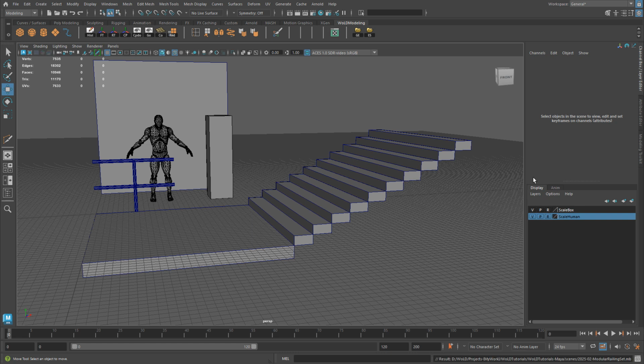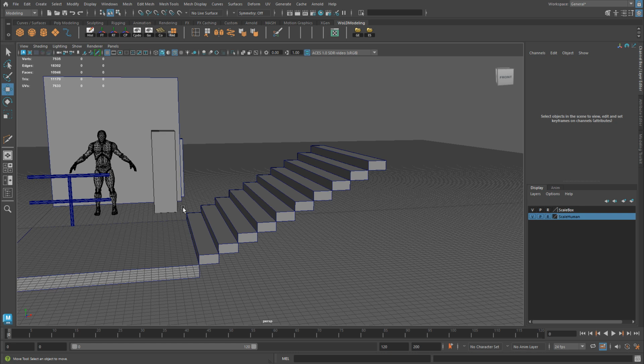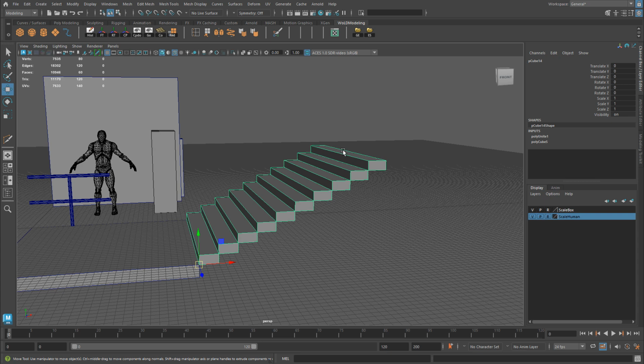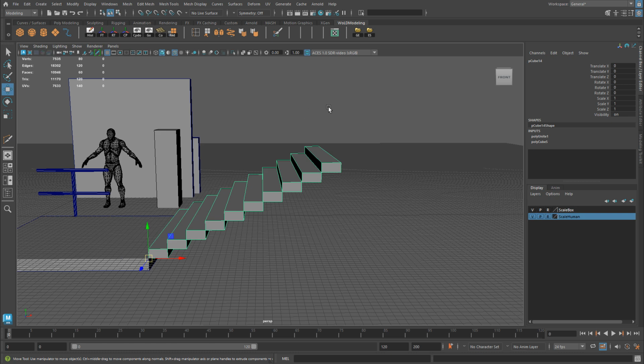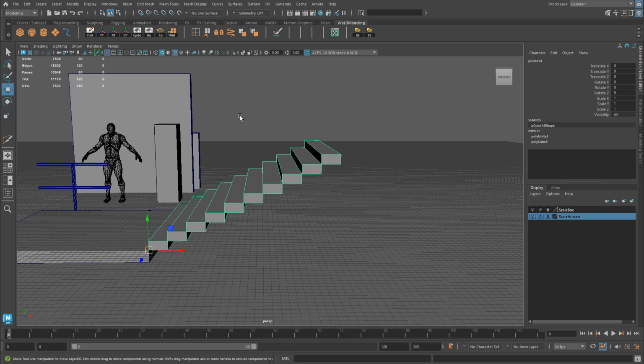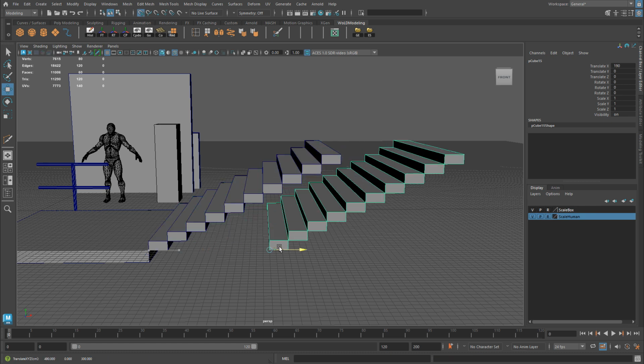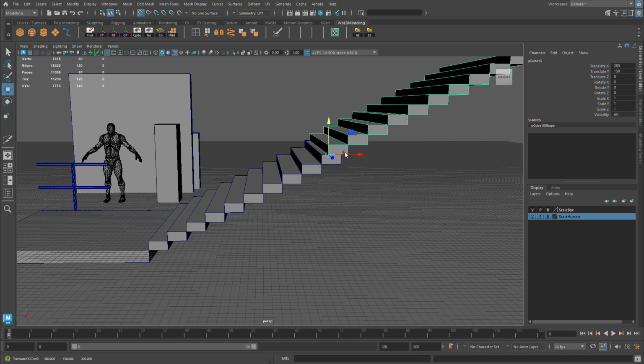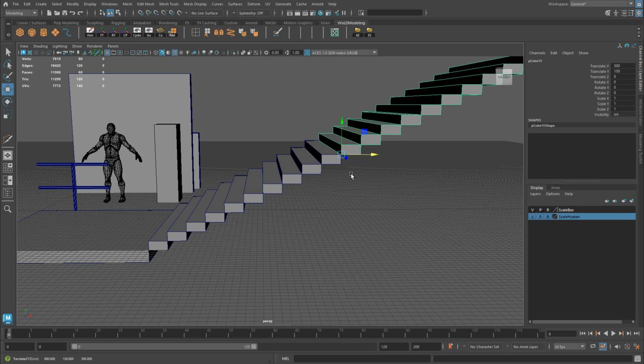For this railing piece, we're also going to create a 150. It's going to expand the same amount of units as the stairs. So the railing will be 300 going up to 150 height, the same as for the stairs. And if we need to continue these stairs as well as the railing up to 300 and make it continuous in order to reach the second floor, we can just reuse the steps as well as the railing, and they will snap to each other.